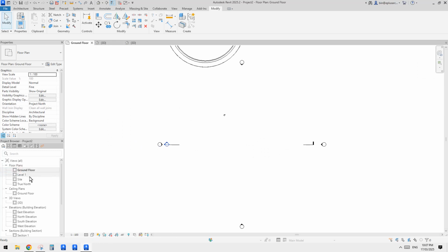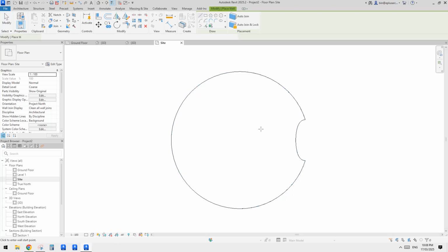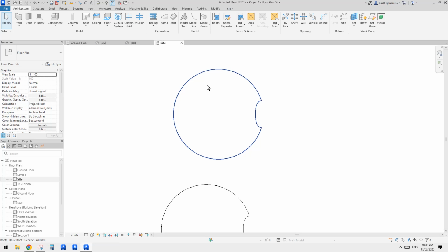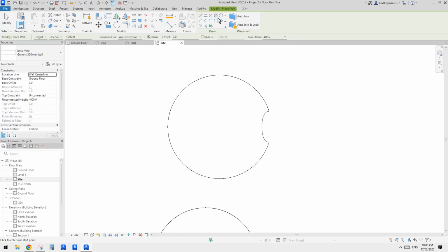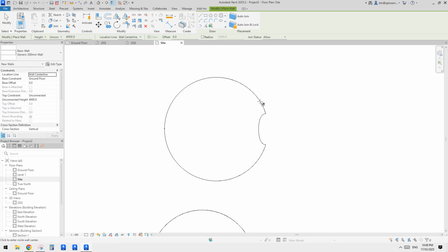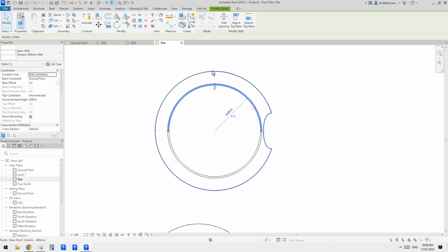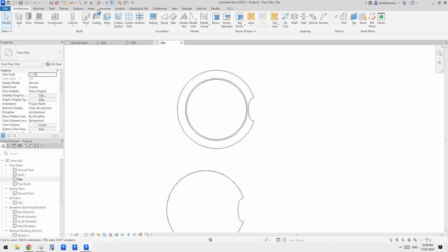And then from this one, let's just go to a site plan. So maybe this one, yeah. Then you can create some walls, for example. I wanted to try this because you might want to attach to the wall. So let me just do a circular wall. I'll use the snap center, SC, to snap the center of this. So we can quite easily create a circular wall to align with the roof using the same center of the circle. And then let's go to 3D view again.